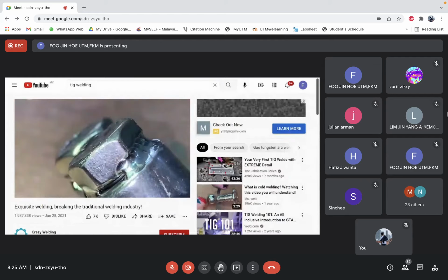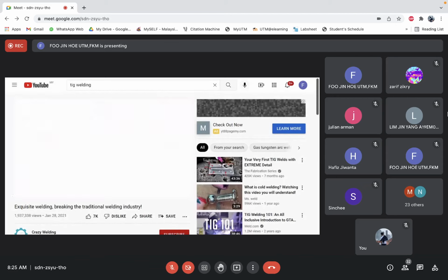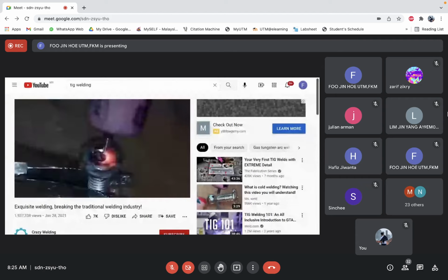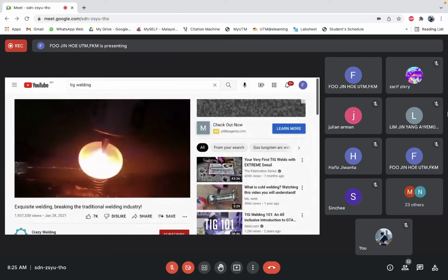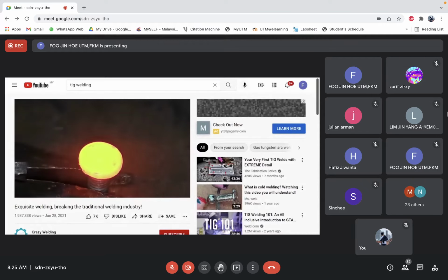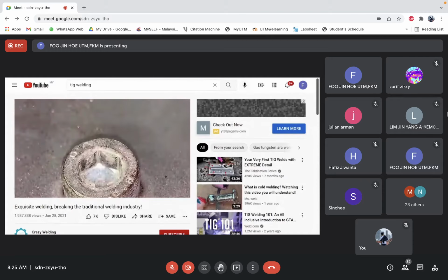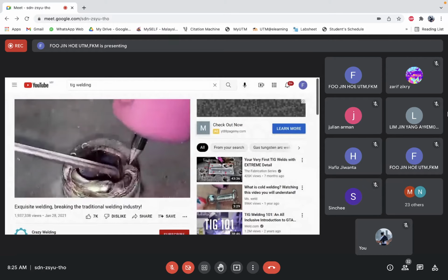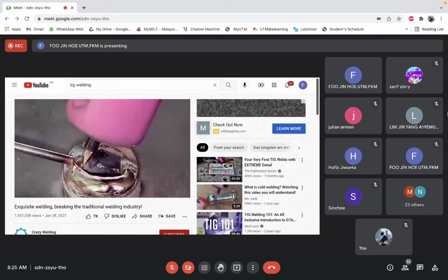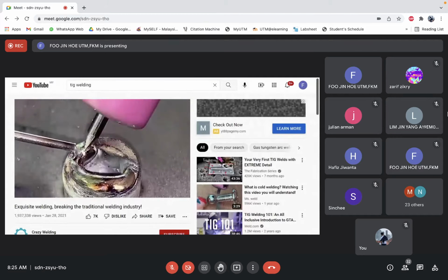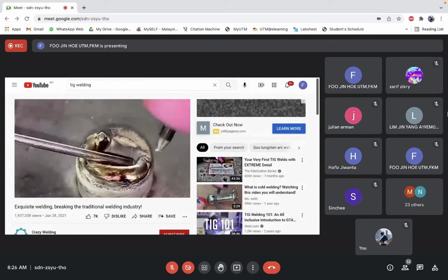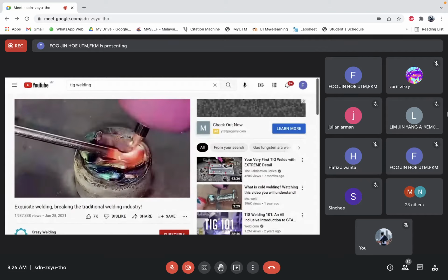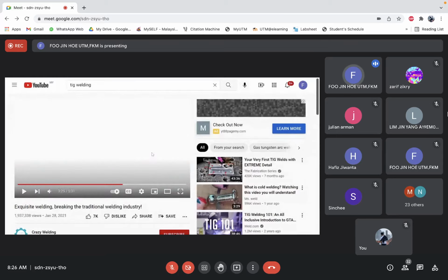Manual arc welding is currently the most commonly used welding method. It is also widely used. According to different welding procedures, structural steel, low-grade steel, stainless steel, and non-ferrous metals can be welded. Submerged arc welding is mainly suitable for the welding of longitudinal circumferential seams of structural steel, low-grade steel, and stainless steel medium and thick plates.